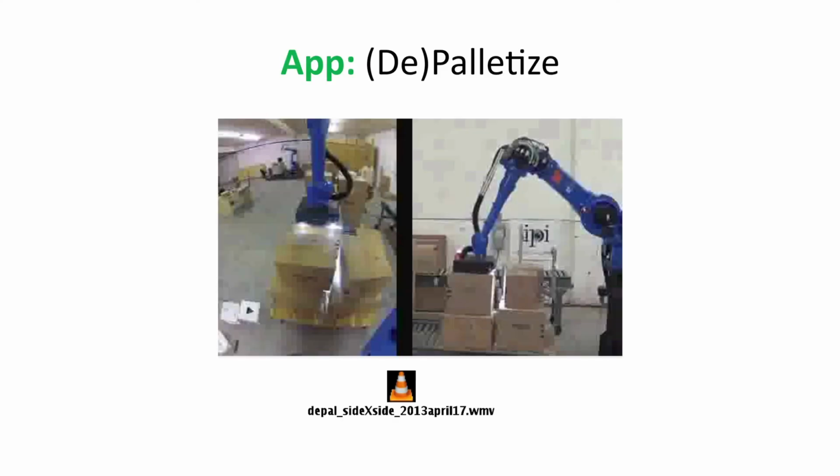So we took that same software and we ported it. This was a 4-week effort from complete scratch, from ordering the robot to bolting it up there to bringing it in. But basically what it's doing is the same kind of thing as truck unloading, but in a different context, which is called depalletization. So, it's going and putting things in a beam breaker that measures the box and tells it where to drop off. And this is something we did, well, it's actually ongoing, but this is 4 weeks from scratch, including building that end effector and putting the cabling on the robot, the whole thing.